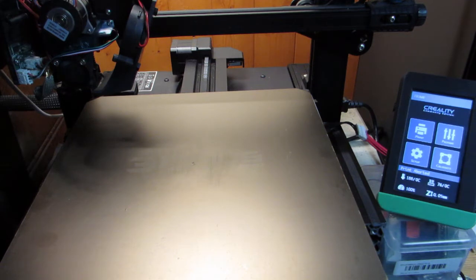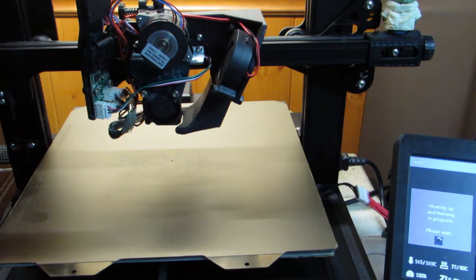I have flipped the bed from the powdered PEI surface to the smooth PEI surface, just to take away any risk that bumps and valleys in the bed pattern make a difference. You may see a scar in the center of this bed. I have been attacked in the past by this printer when it decided not to stop when the nozzle hit the bed. It's one of the vulnerabilities of PEI sheets, as they can be gouged and divoted by the nozzle on this printer.